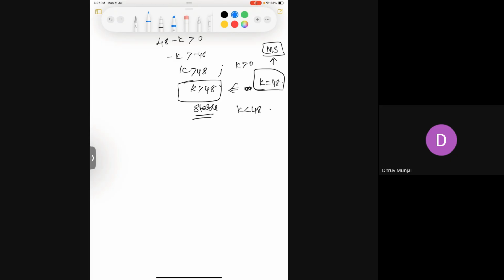I said it goes from poles to zeros, but we have 3 poles and 0 zeros, so there is no way a pole can extend to a zero. So all 3 poles are going to go to infinity, maybe minus infinity or plus infinity based on the location of poles and breakaway points. Now we are plotting the root locus.